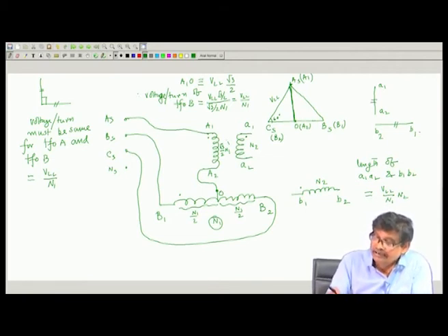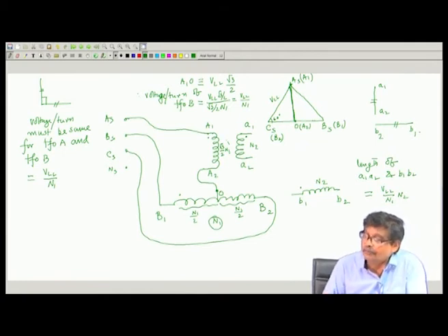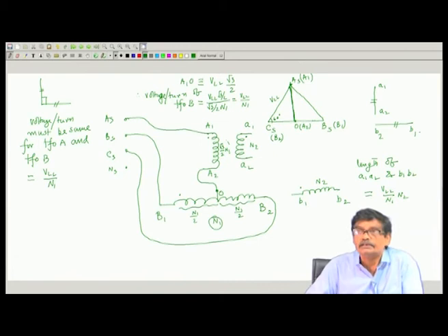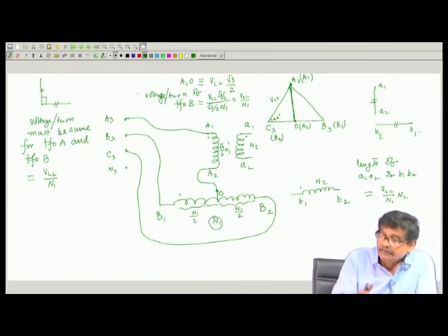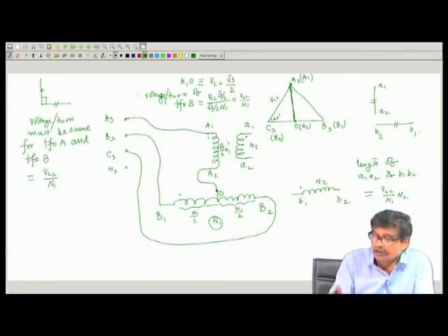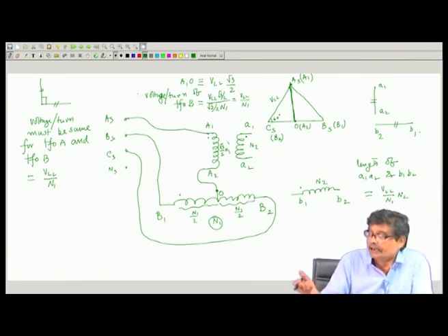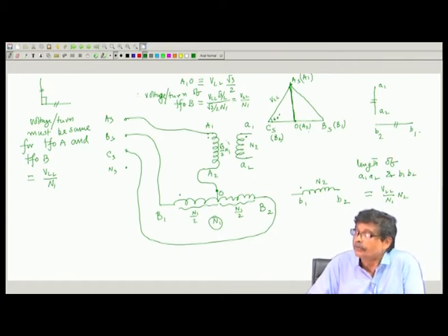So, you see, at the secondary coils of these two transformers there exist two voltages whose magnitudes are the same and which are 90 degrees apart. So it was a balanced 3-phase voltage, and on the secondary coils, although I have not connected them yet, I get a balanced 2-phase voltage.